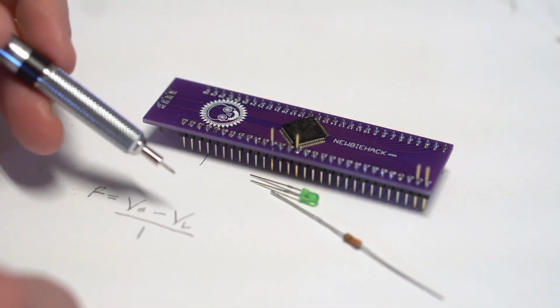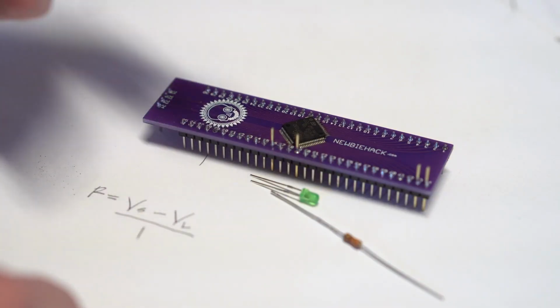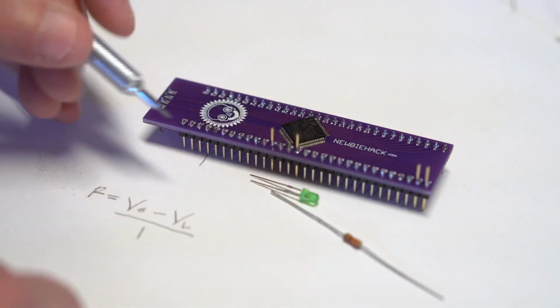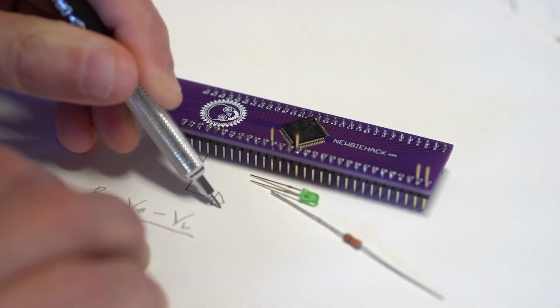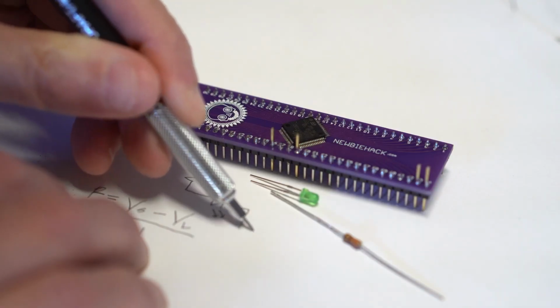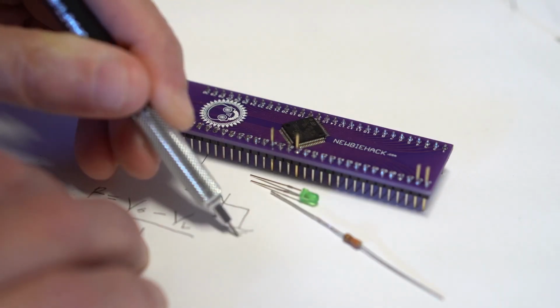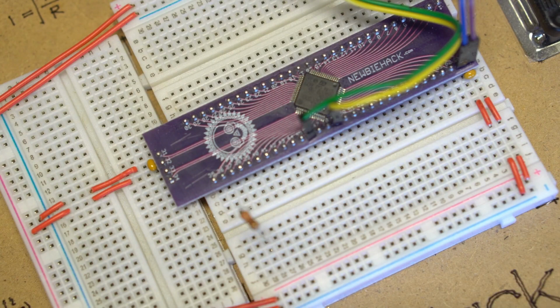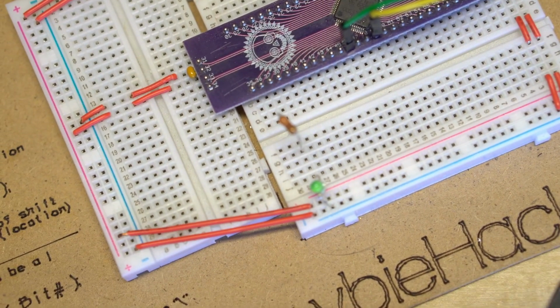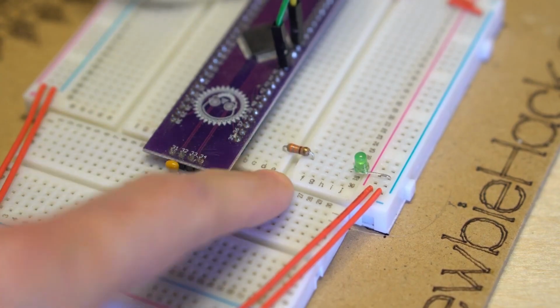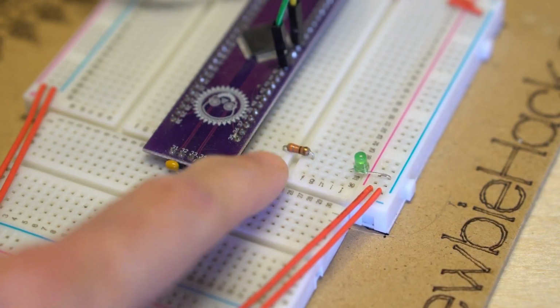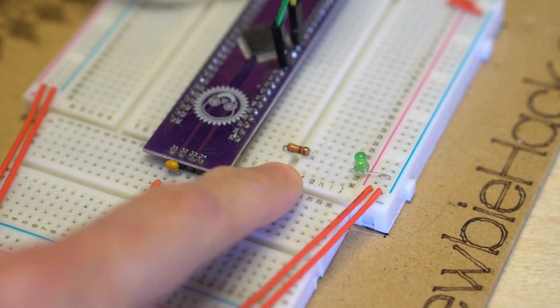Let's draw the schematic. You're going to put the resistor in line with the LED. So let's draw the resistor. So this is what the resistor would look like. And now let's draw the LED symbol. And the LED will be connected to the ground power rail. Let's add the resistor and the LED to the breadboard. Make sure to have the LED oriented so the flat side of the LED is connected to the ground rail. Okay, I fixed the circuit so it's a little bit less ugly, and it probably serves better and doesn't act as antennas.